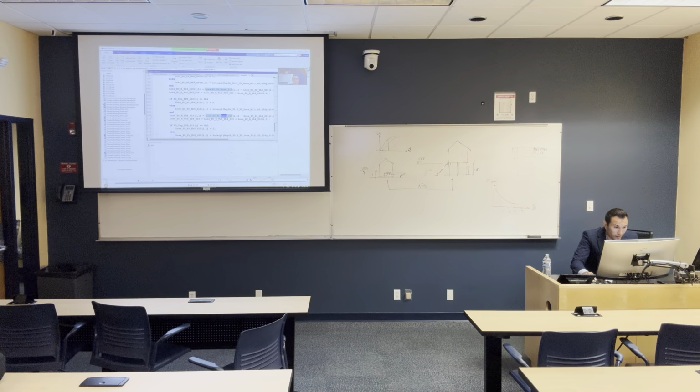Let's see what I did over there. Okay, look at this one, loss fragility base doesn't have elevated components, okay? And this one base doesn't have elevated components. So anyone that has base, remove the elevated component from it. Okay, once you click on one, it's going to show you all the ones that have base scenario. 1, 2, 3. Just delete them one by one, and it's going to be fine.